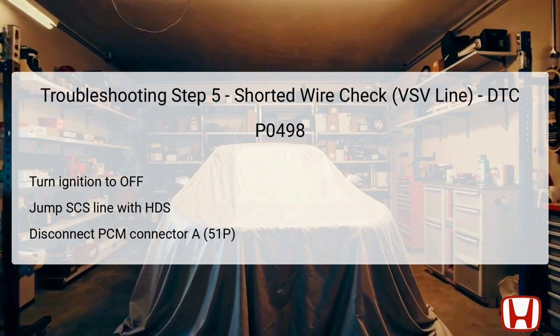This tells whether the VSV wire is shorted to ground or other circuits. If continuity exists, it indicates a short, which must be repaired by inspecting and repairing the wiring between the vent valve and the PCM. Resolving wiring shorts ensures proper voltage signals, preventing false DTC triggers.